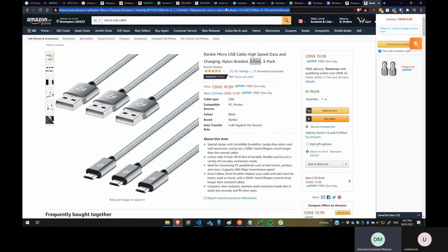The Arduinos on the pod are going to be very close to each other, right? Wait, what are you using these wires for? To connect the Arduinos and the Odroid, which are going to be on the pod. Wait, do the Arduinos need to be connected to the Odroid the entire time? I thought the point was them using network cables, so they don't have to. You can have wired or wireless network, but with wireless, it's more likely that you're going to lose packets of data.